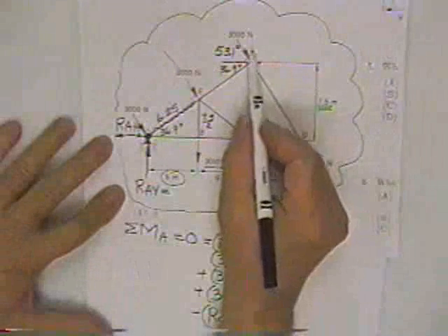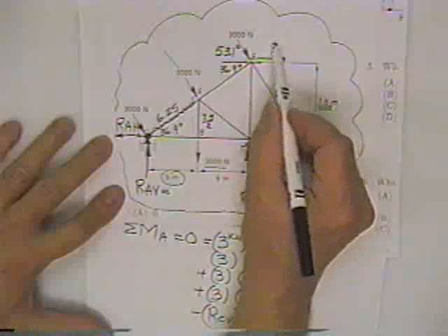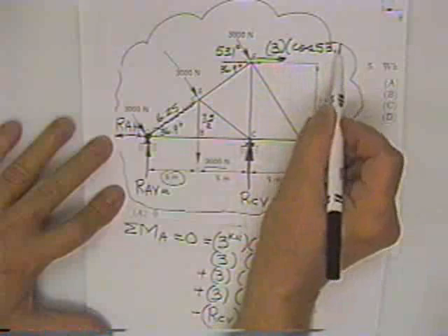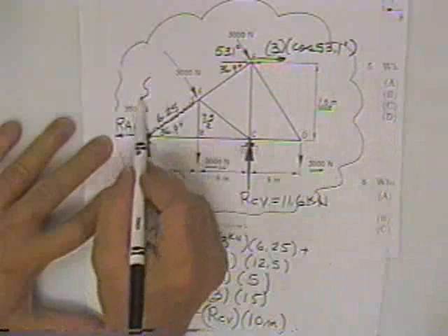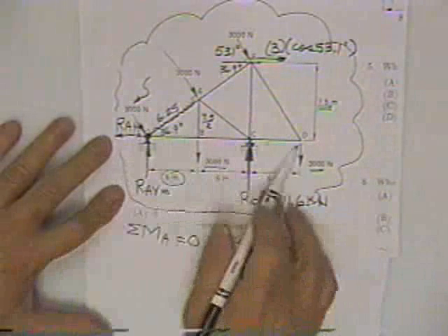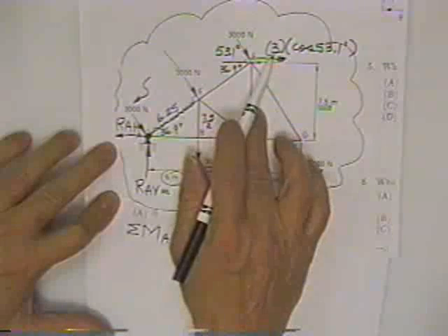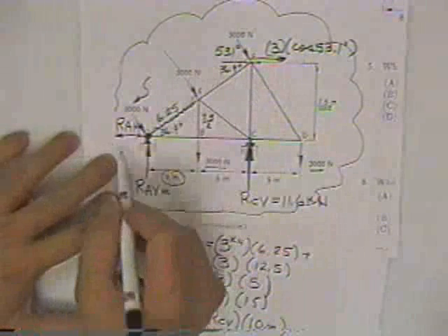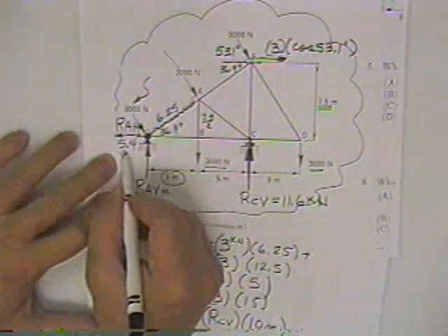So here again, we will find the horizontal component of this one by 3 kilonewtons times the cosine of 53.1. There'll be another one here. Don't forget this one here. This one counts. There'll be 3 of those. Those are the only people pushing to the right. This will equal 3 times cosine of 53.1 times 3 of them. What'd you get for that? 5.4. 5.4 kilonewtons.